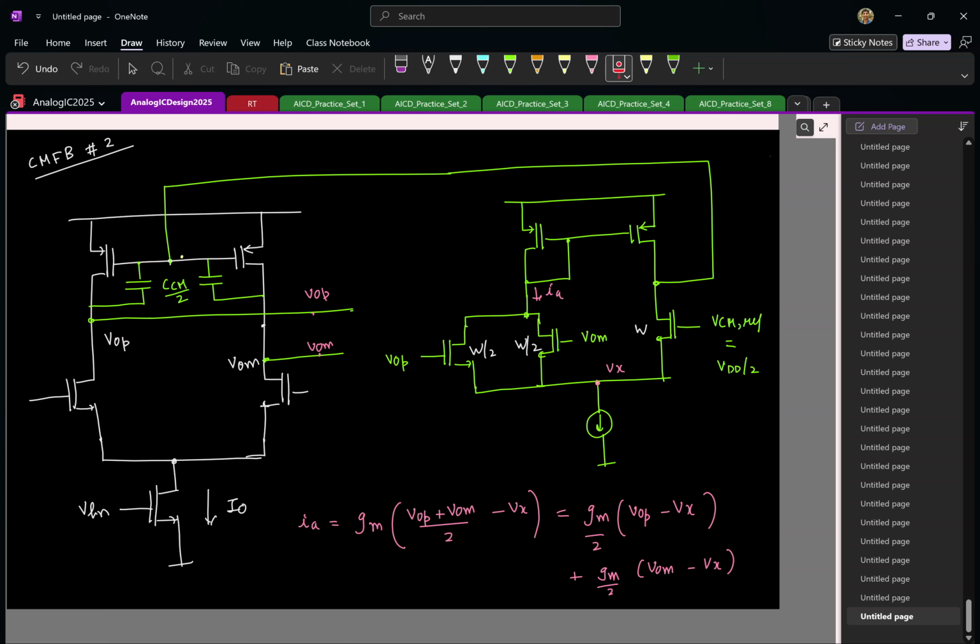So this way we can avoid any kind of resistive loading because we are directly connecting gates of the transistors, so you will not have resistive loading. But of course the gate capacitance will be there, capacitance loading will be there. That is something you can't avoid. So I'll call this variant 4.